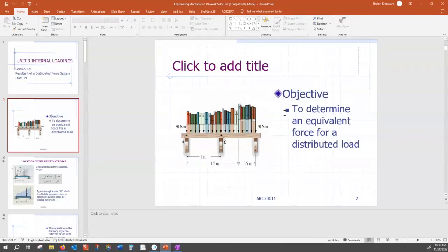The answer to that question, you should know, is that a bar or two force member can only become longer or shorter. Examples are individual members inside the truss structures. Many other mechanisms or machines or frames might have two force members, three force members. But the thing with the beam, specifically, is that a beam allows the transfer of the load from one support to another support by the action of bending.